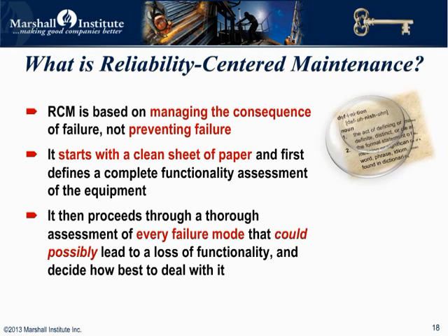The RCM breakthrough was the realization that maintenance is not about preventing failure, it's about preventing the consequence of failure. Some kinds of failure can't be prevented. Even normal wear and tear leads to failure. You can't prevent that. What you can do, though, is make sure that it doesn't bite you in the butt, so to speak. That is, do something before the failure results in loss.